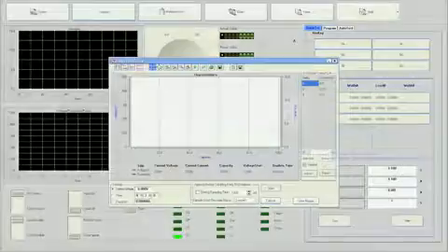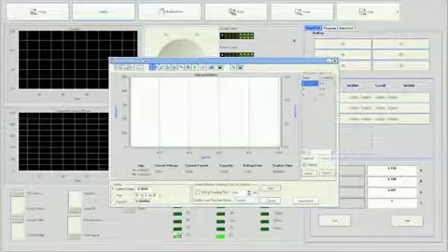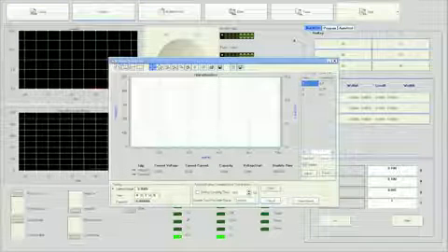The battery discharge window will open, and the main screen illustrates a graph with labels for voltage, capacity, and current. On the right column, a discharge current list is available for users to create custom discharge profiles for dynamic testing. Let's enter a few steps in the list for testing. Keep in mind the left column specifies delay and right column specifies current.